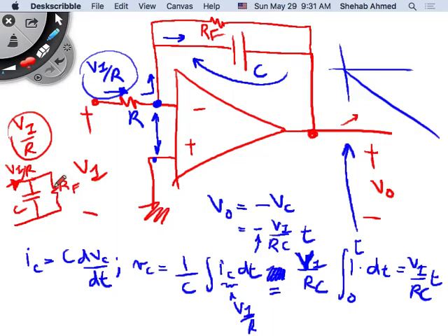So it will tell me the value of the final voltage across this combination, right? Do we agree? Assuming I keep this current flowing into this combination for a long time, the capacitor will become an open circuit eventually, and initially the current will flow in the resistor and capacitor combination. It will flow through both, and then after a transient response, the capacitor will charge, increasing its voltage until some maximum voltage. What is this maximum voltage equal to in this case?